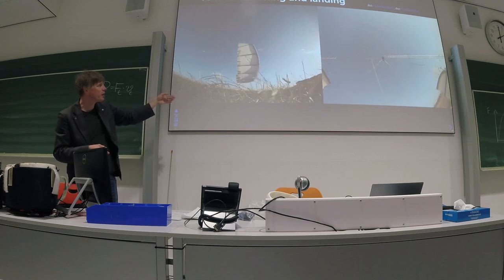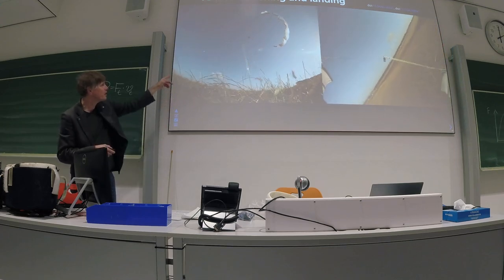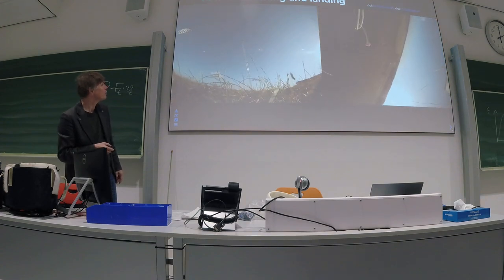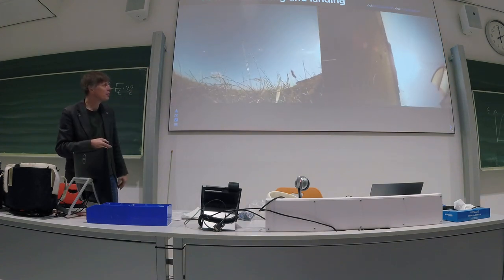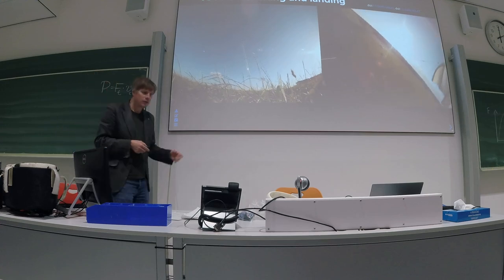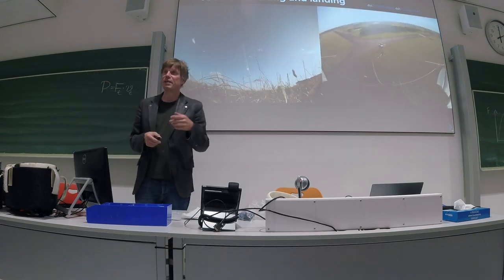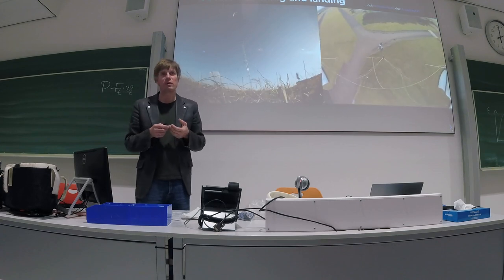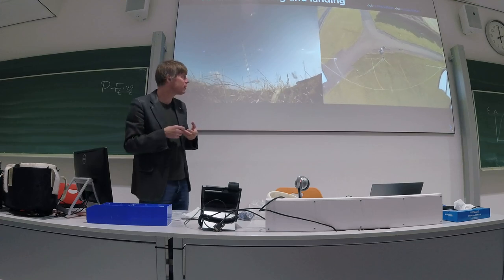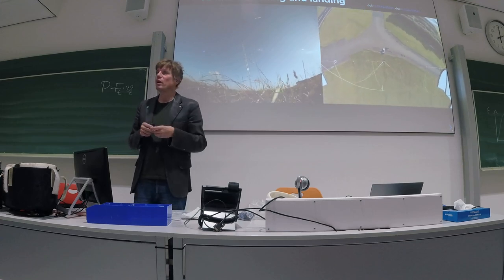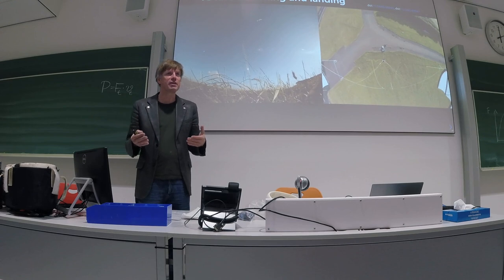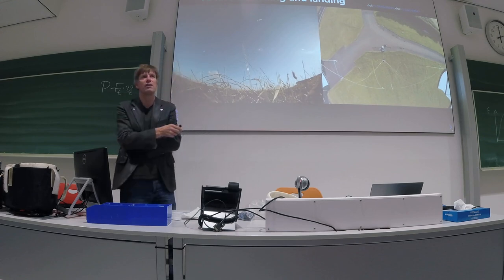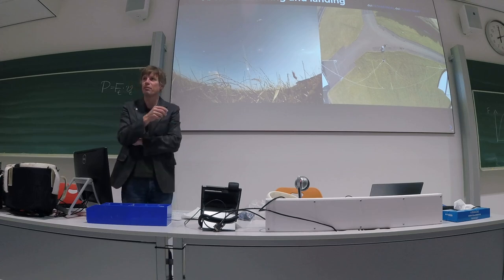This is the launch maneuver, synchronized from 2 different cameras, onboard to the right and offboard here. You see how this maneuver works, and then the kite flies off. From many different trials, this was one of the few that actually worked. That was the real difficulty of this launch maneuver: with the very low wind speeds that you have on the ground, you have to fly the kite in this loop maneuver to launch off.